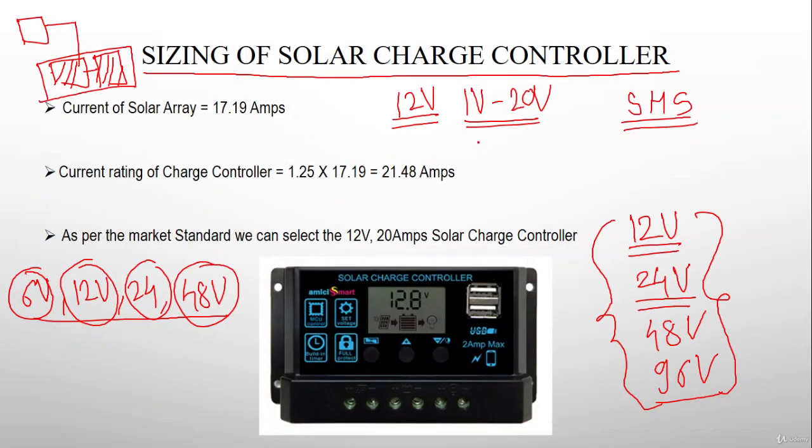In the solar MPPT charge controller, we can accept the maximum amount of voltage from the solar panel and give the rated voltage for charging the battery. If we are going for a cost-cutting application and selecting a PWM, pulse width modulation, solar charge controller, then we have a limit on the maximum voltage that we can send to it. But second, though we select an MPPT solar charge controller, it also has a maximum limit on the voltage we can send to it.